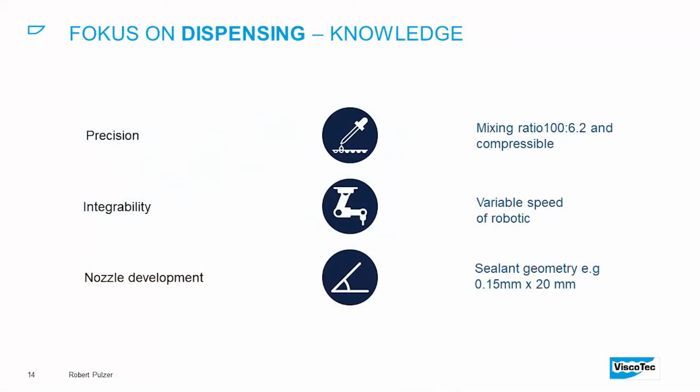Integrability: when you have not only the dispensing system standing alone, when there's a robotic or XYZ system integrated, the dispensing head, the dispensing system, and the robotic must function 100%. When the robot is moving faster, the dispensing system has to adapt to this speed immediately.